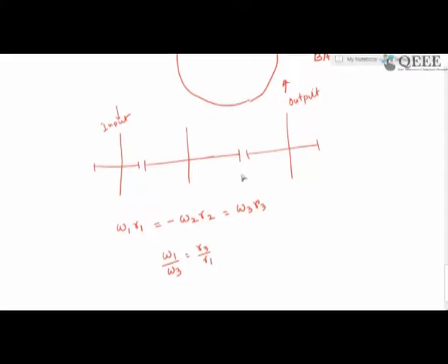What the second gear is actually doing for us is maintaining the same gear ratio while enabling the mechanical transmission to happen over a larger distance. Suppose we want the power to come out at a further distance. For example, in commercial vehicles one really has to transmit the power from the engine to the rear axle. That's a pretty large distance. Actually in a rear axle the power is transmitted through the universal shaft, but this is one case where we can quickly think of a situation where the mechanical power needs to be transmitted over a larger distance. So simple gear trains are used for such purposes.